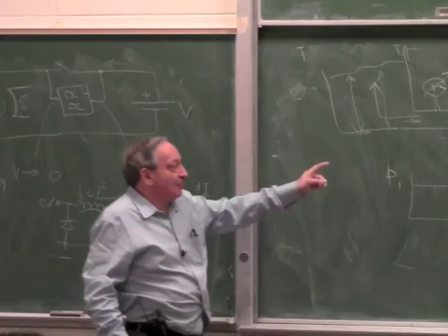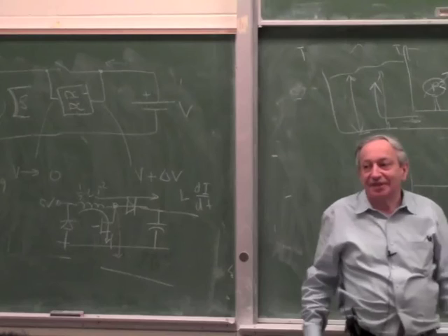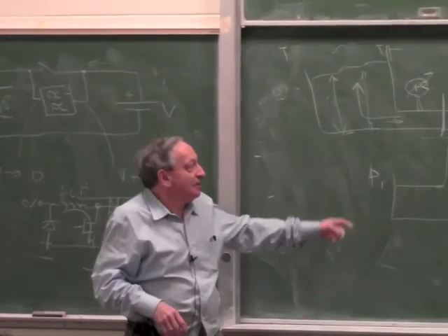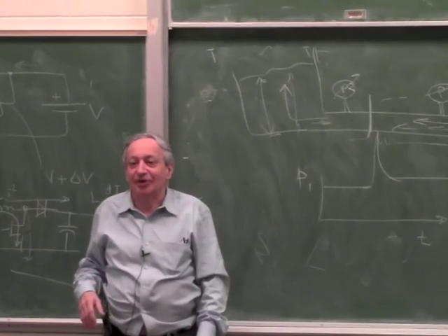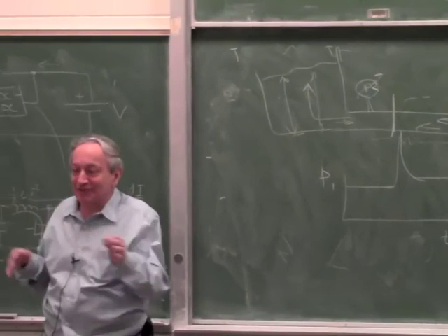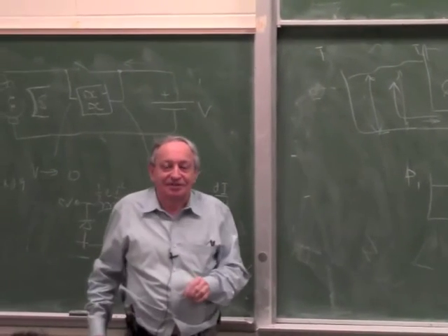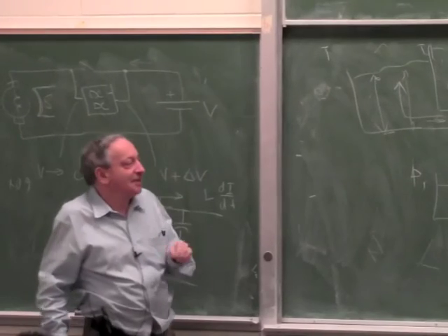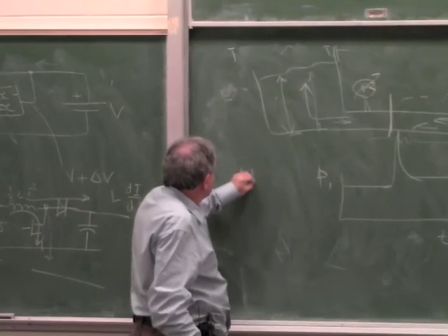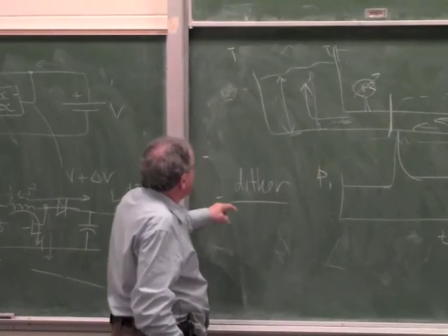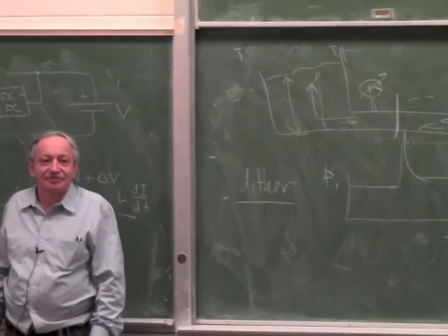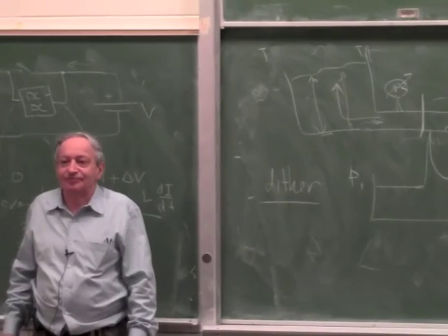And the curves of the hydraulic motors and pumps are exactly the same as the curves of electric motors. Except in here it's all DC. There is no AC fluidic systems, AC meaning the fluid goes back and forth. It doesn't exist. The nearest thing to an AC fluidic system is something they do in hydraulic servos called dither. They do it also in electrical servos, but mainly in hydraulic. Does somebody know what dither is? That's a very clever idea, actually.